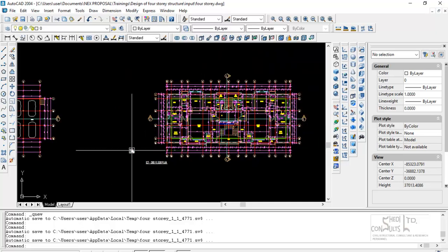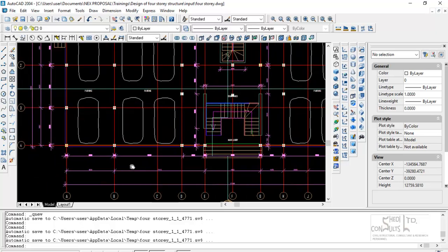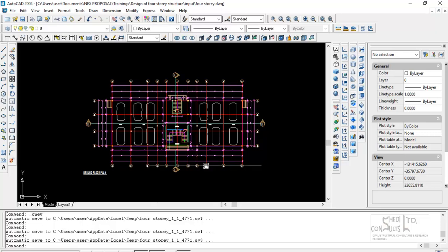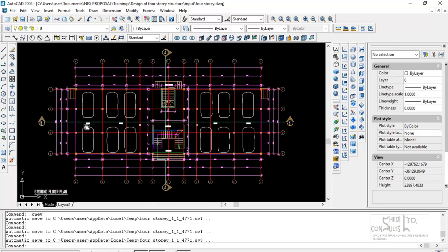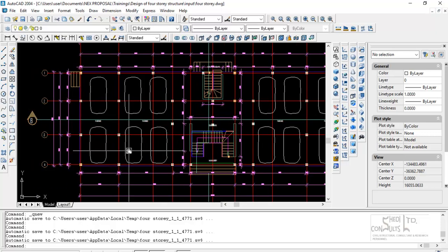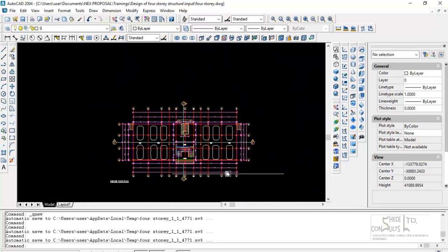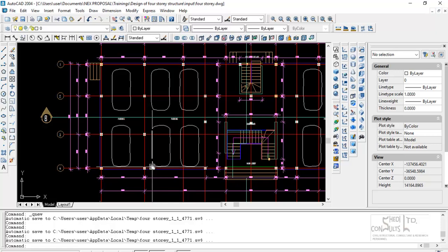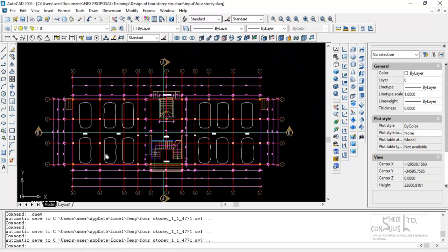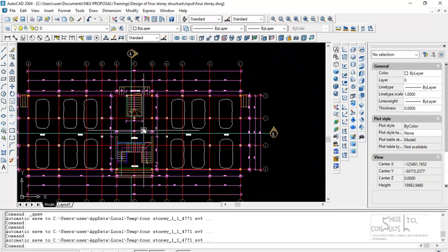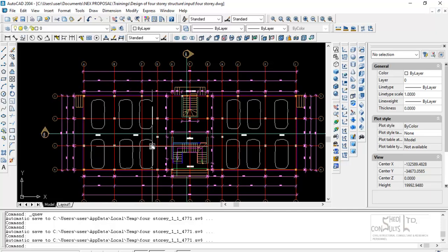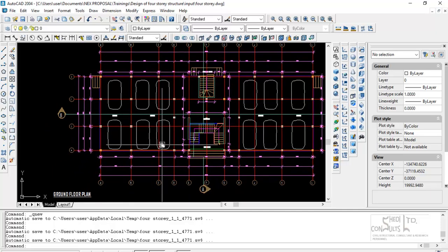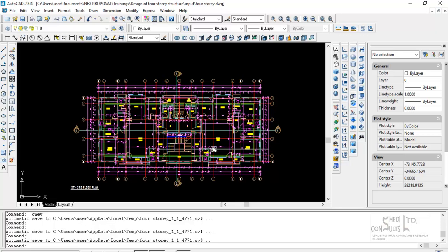Now, when we receive this structural drawing, we study the structure and obtain the subsurface investigation reports, otherwise known as the geotechnical investigation report. The geotechnical investigation report will give you information on the subsurface characteristics of the site. It will reveal the soil stratigraphy, the vertical sequence of stratified soil, the lateral extent, and the nature and location of the groundwater table.